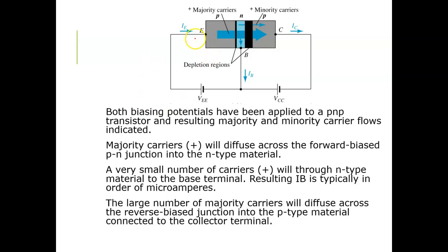Similarly, what is the base-emitter voltage? Like the diode conduction voltage, when the transistor is conducting, the base-emitter voltage is 0.7 volts. And when the transistor is fully conducting, the saturation voltage VCE(sat), the voltage across emitter and collector, is 0.2 volts. That should be remembered. This is very important for your understanding.